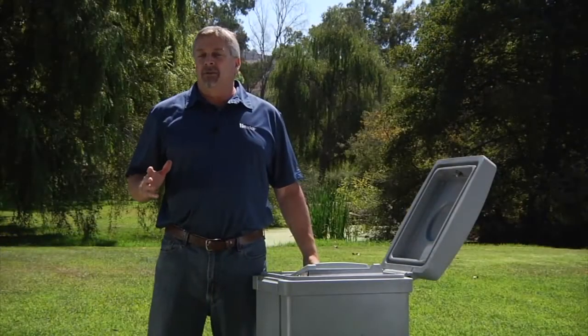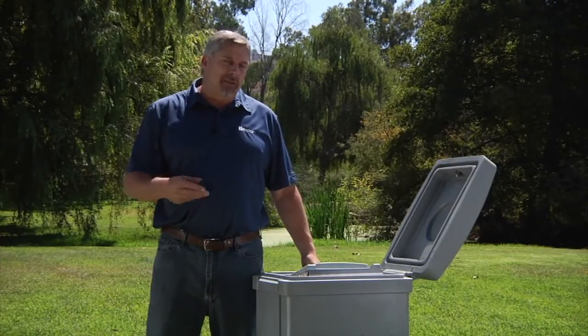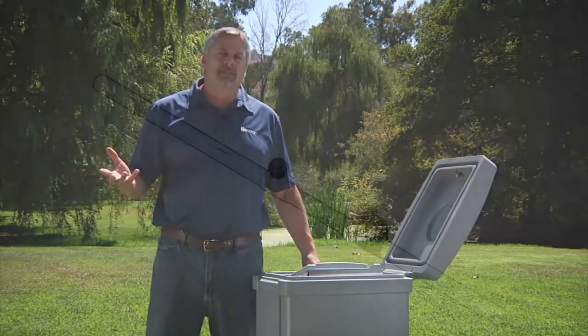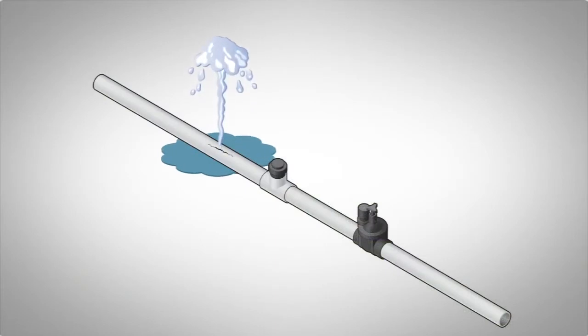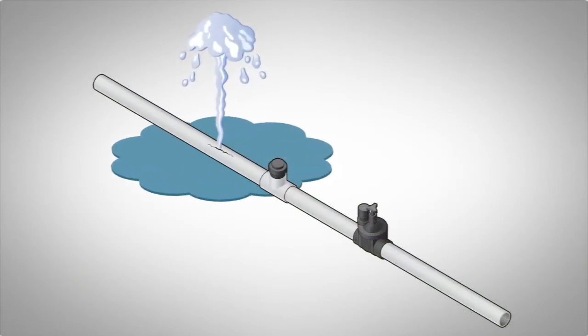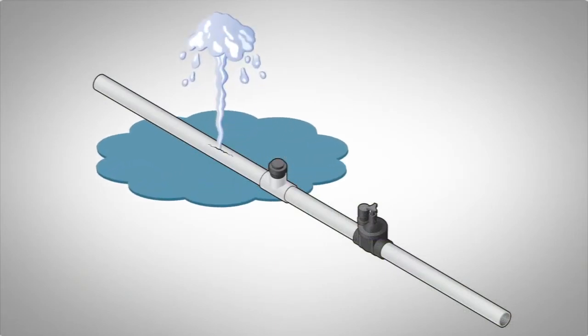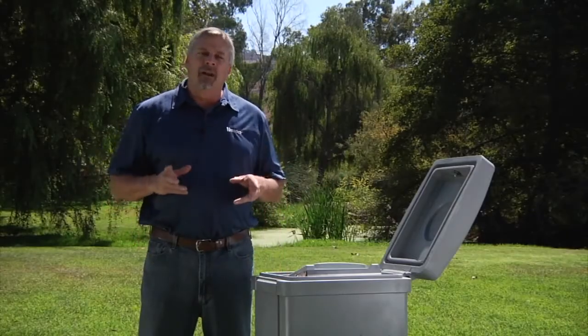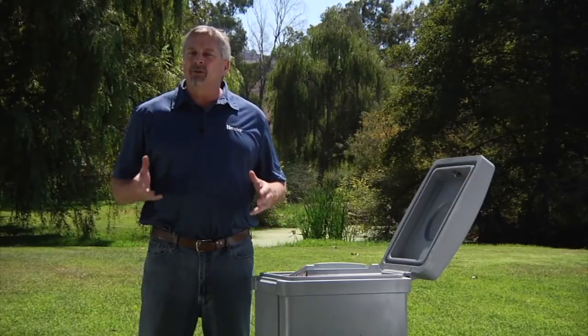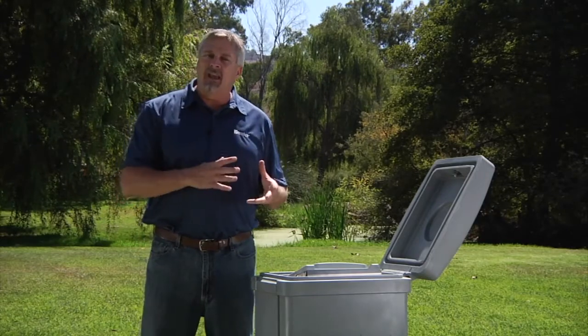All ACC controllers have the ability to monitor flow, and it's relatively inexpensive to incorporate a flow sensor. One of the main reasons to install a flow sensor is to prevent geysers caused by broken lines or broken sprinklers. Another reason that flow monitoring is important is that it keeps a record of the flow value by station and/or by program.